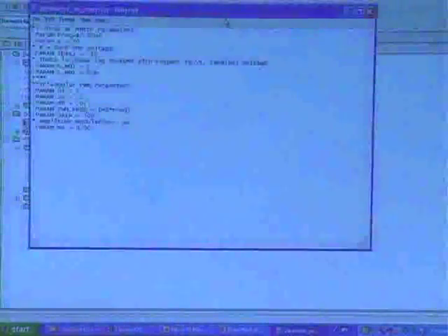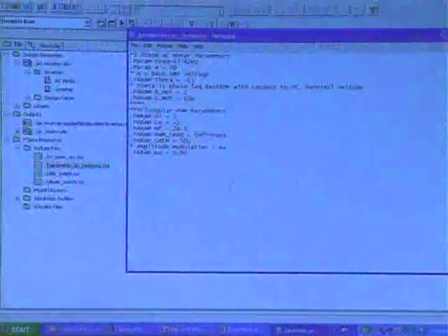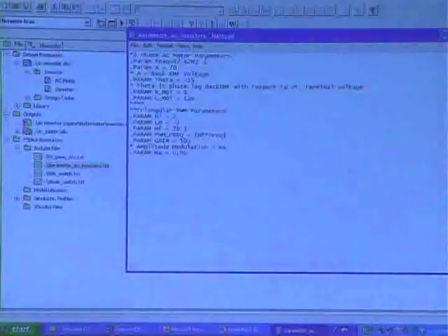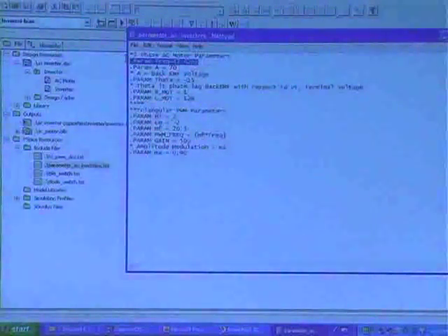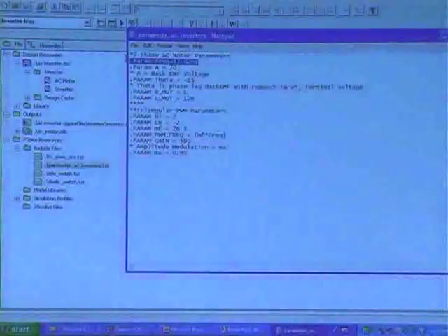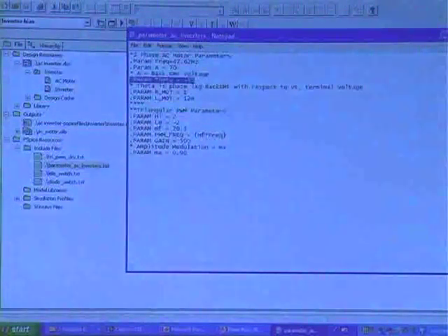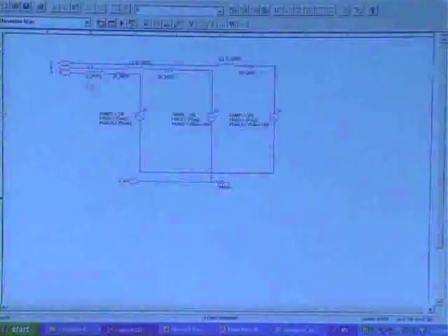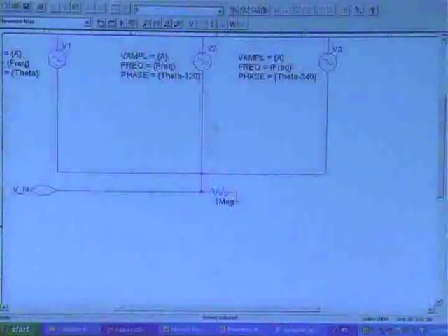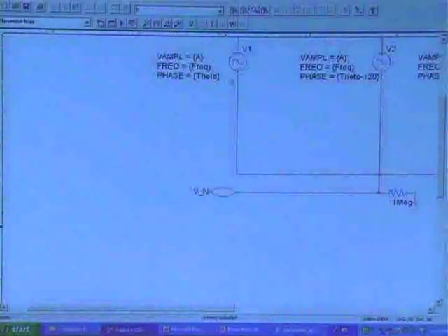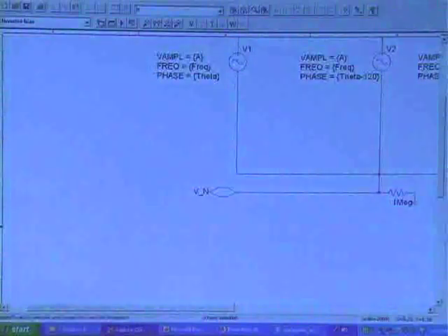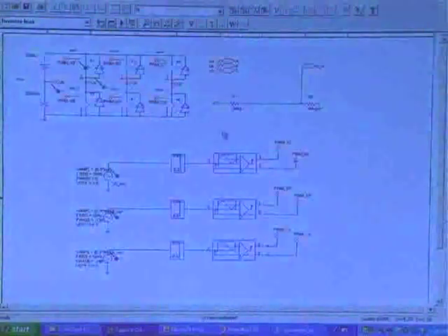So the frequency is 47.62 hertz. This is the frequency of the rotation of the motor. Back EMF about 70. We have a phase lag of minus 15. So if you look at the motor, we have a theta here. So that's a phase lag of minus 15 degrees.